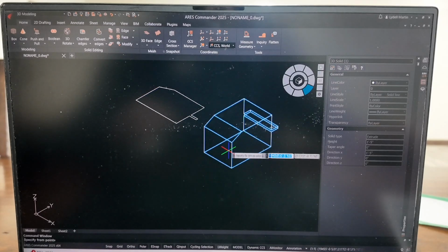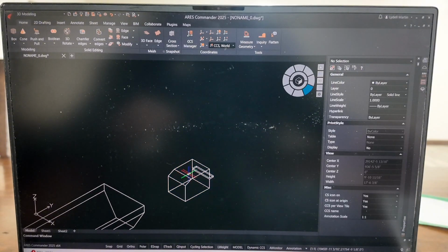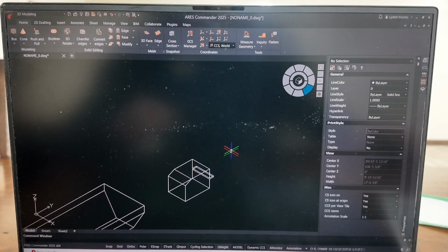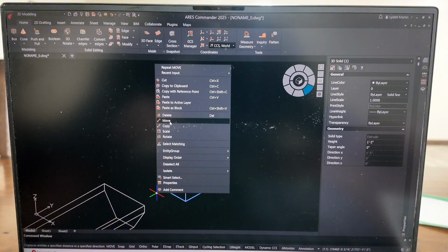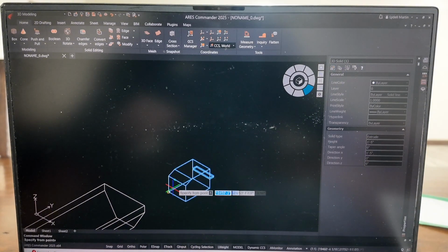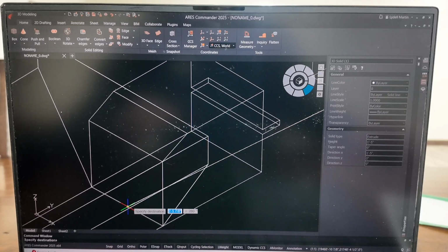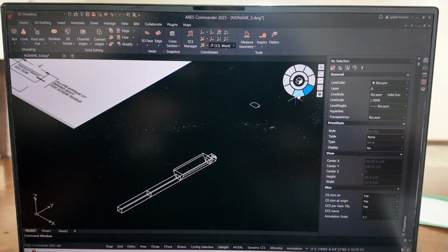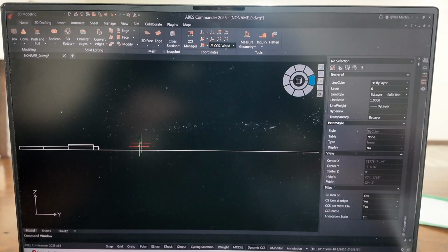Now we're going to select move. Going to select the top center of the tail here. Actually, that's not going to work. We're going to escape and then hit. Select it. Right click. Move. And we got to hit the bottom center of the tail. And go to the bottom center of the dump pit. And we're building a drag conveyor.